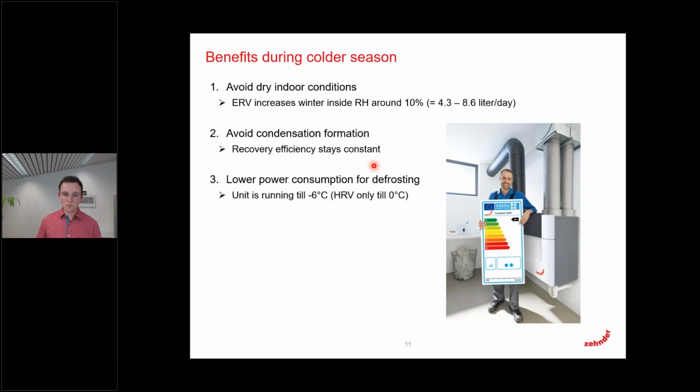And what is also important, you have a higher recovery efficiency because the condensate, which occurs in the standard heat exchanger, blocks the heat transfer. So if there is condensate, you do not have the full recovery rate. So you do not only have a higher recovery using an ERV because of the use of sensible and latent energy, you also have a constant recovery efficiency.